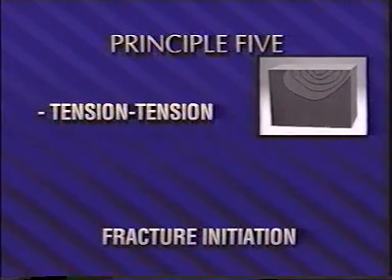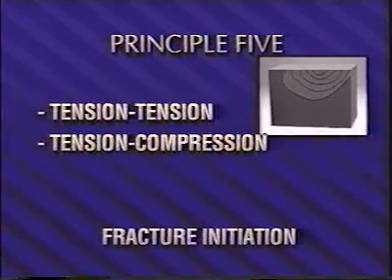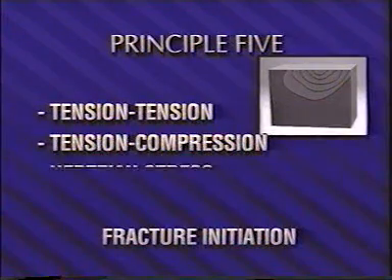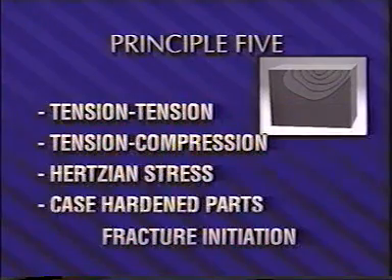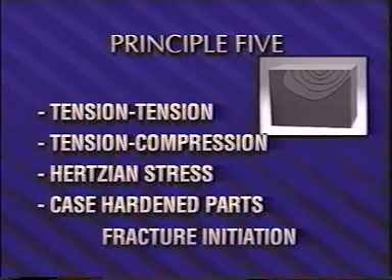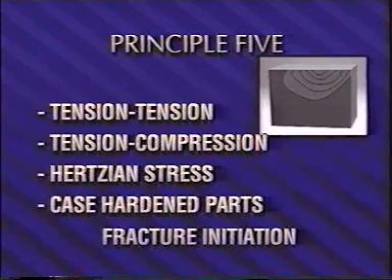Subsurface origins have been observed in tension-tension or tension-compression fatigue, in Hertzian stress situations, such as the rolling contact fatigue of bearings, and in bending or torsion of case-hardened parts with no external geometrical stress concentrations. Crack initiation at the corners or at the ends of drilled holes may result from the presence of burrs remaining after machining.